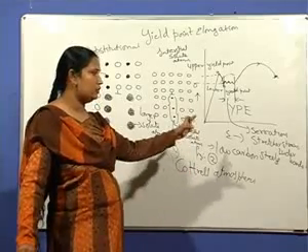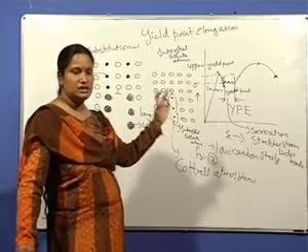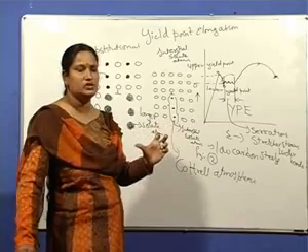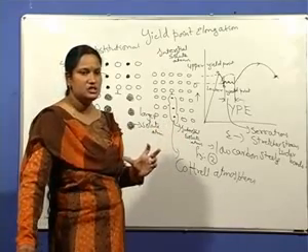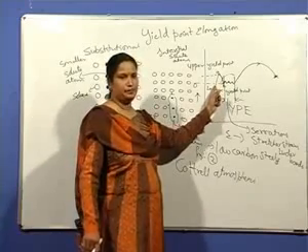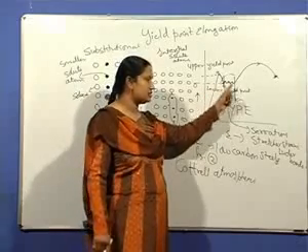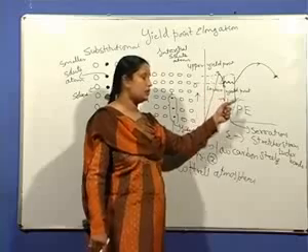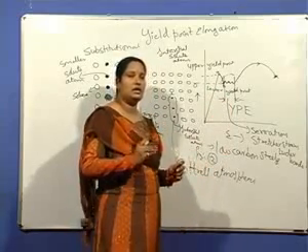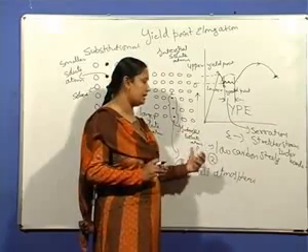Whereas for the case of low carbon steel, up to the point A, the stress strain curve is similar to the normal curve. At point A, the material suddenly undergoes yielding. Dislocations move very easily. Stress drops. The point B is known as the lower yield point, beyond which the serrations or structure strains, also known as Luder bands, are seen. Why? Because of locking and unlocking of the dislocations by these interstitial elements like carbon and nitrogen,